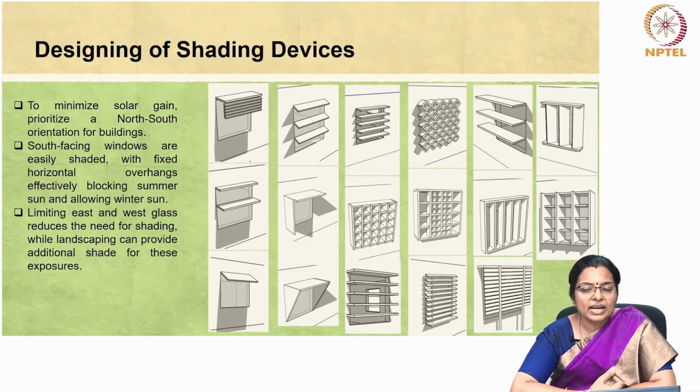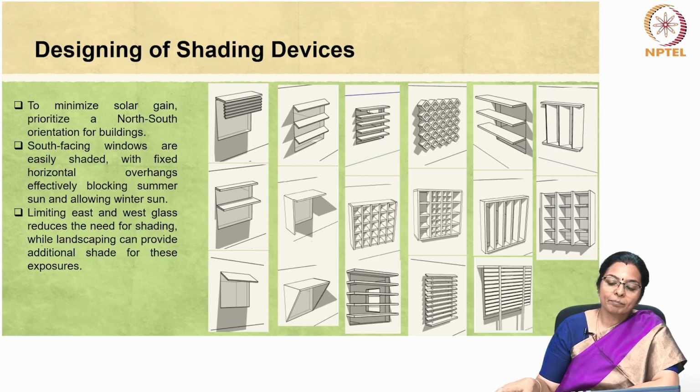So, to enhance natural light, passive design strategies such as light shelves are very useful for deeper and uniform distribution of light, which are most effective on south side of the buildings, and these are mostly recommended in milder climates and definitely not for tropical or desert climates.